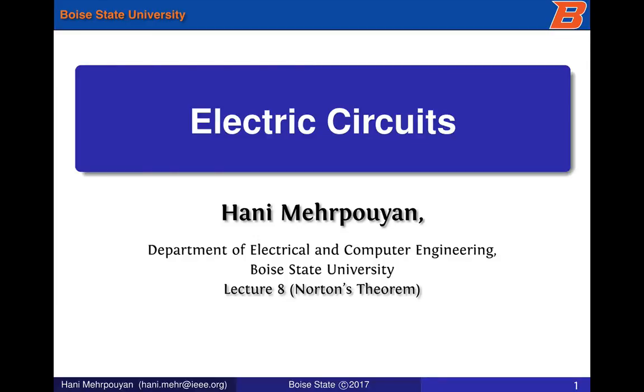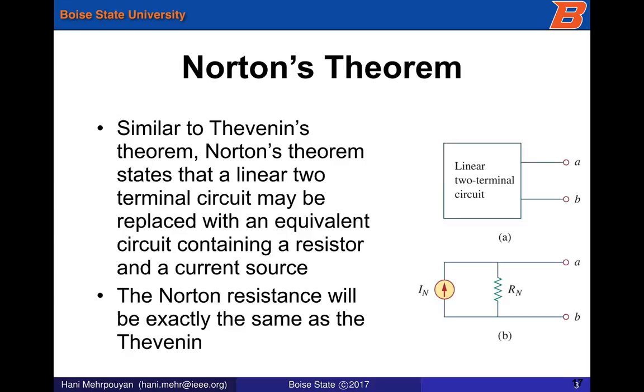Hello everyone, today we'll be discussing Norton's theorem and maximum power transfer. So Norton's theorem is closely related to Thevenin's theorem, and the idea here is that instead of representing a circuit with a voltage source and a resistance in series with it, we could also represent it with a current source and a Norton resistance in parallel with it.